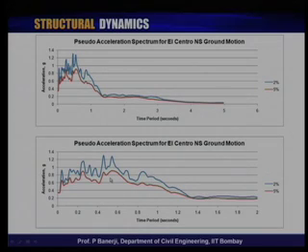And although the design response spectrum is not based on one ground motion, it is based on many ground motions. So, the peaks and valleys that you see in any one particular ground motion actually get evened out, and you will get somewhere over here. So, this is 0.3, for 5% it is about 0.8. So, that is about 2.67. If you go to 2%, this is about 1, so that is about 3.2.